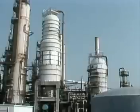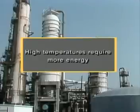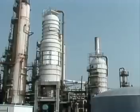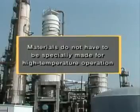A second reason for using vacuum distillation is that running a tower at high temperatures requires more energy or fuel. Operating a tower at lower pressures allows the distillation process to be accomplished at lower temperatures, which requires less energy. A third reason for using vacuum distillation is that a tower that's designed to operate under vacuum, and therefore at a lower temperature, can be constructed of materials that do not have to be specially made for high temperature operation.